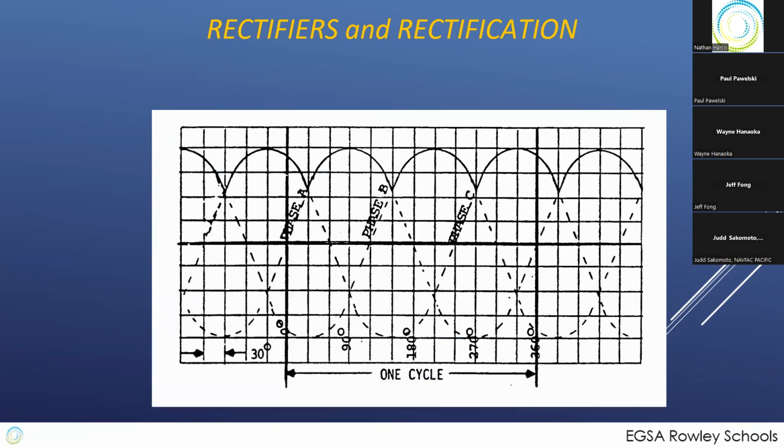And if you look at how the DC power looks, it basically looks like the top part of our three-phase sine wave. We're running along the bumps on the top. We never go to zero, but we do have quite a bit of dip. This can still be a problem if you're running microcontroller loads off of this, because depending on how much drop you've got on the lines going from your generator to your electronic equipment, this can drop into the brownout range for them.